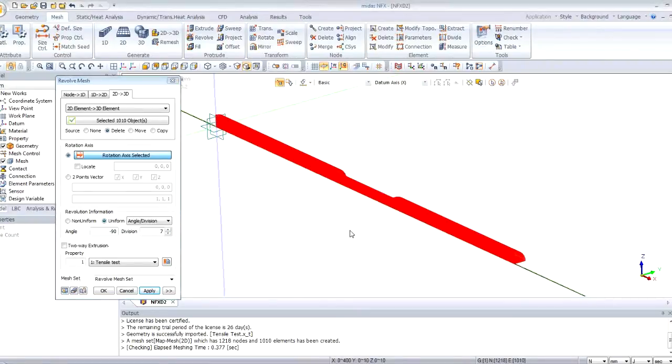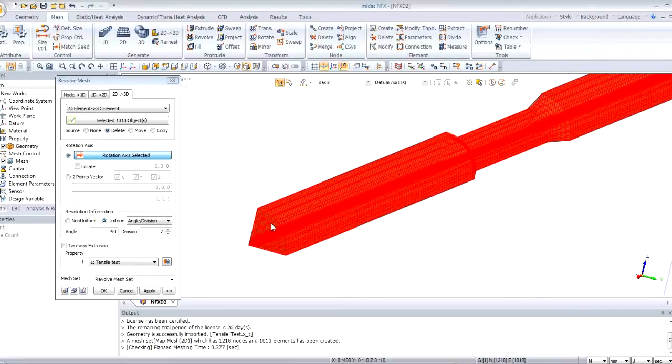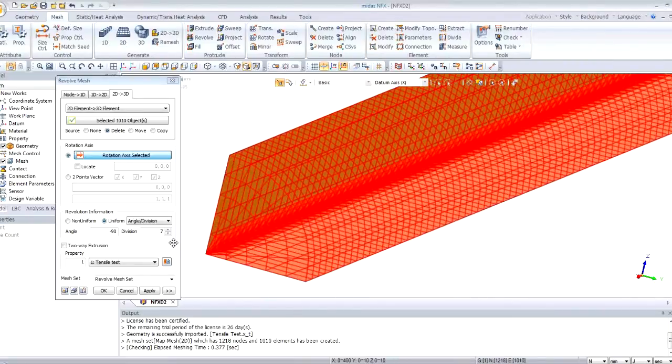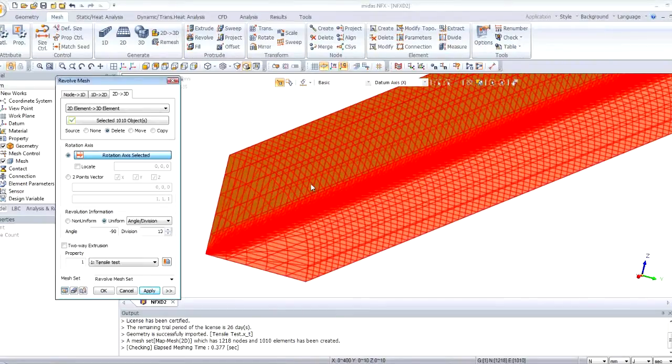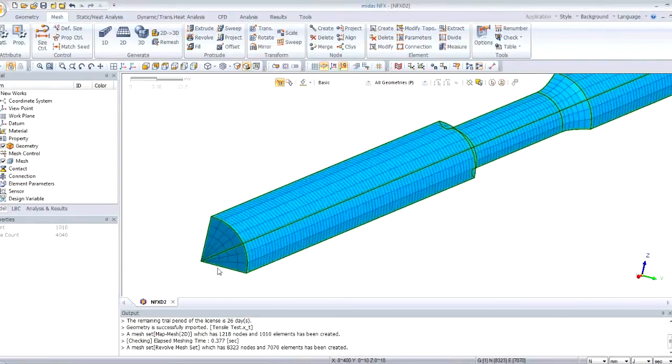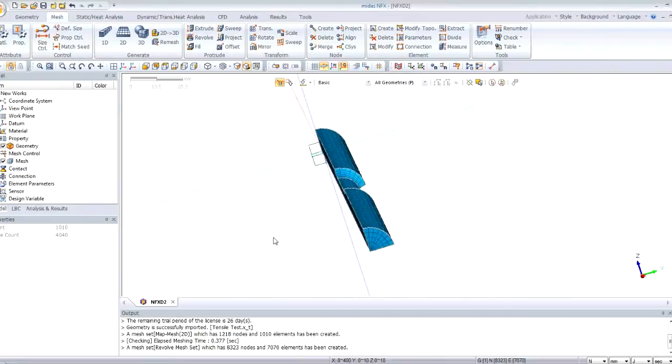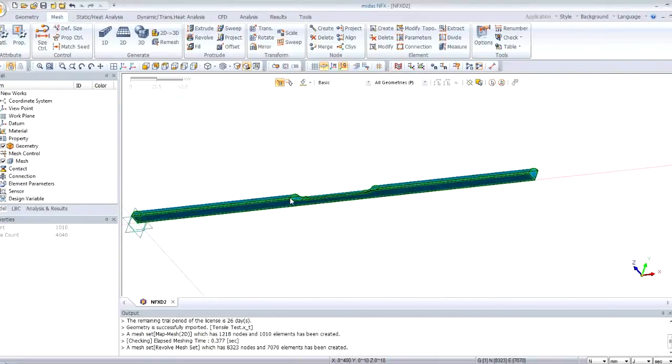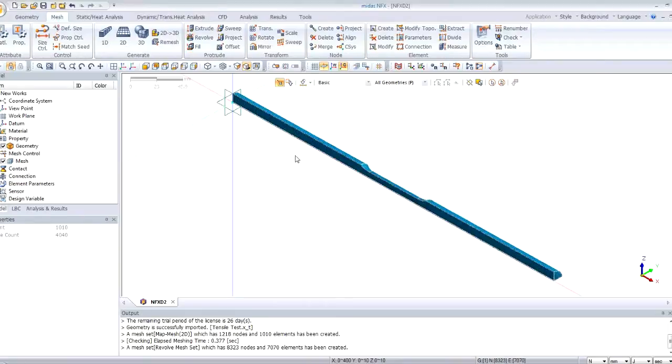Let's look at the preview. Let's zoom a bit to view. Looks good. So if I increase the number of divisions, let's say if I choose 10, it will look like that with smaller mesh, but actually it's a bit too small, so I just choose 7 and click on OK. Okay, now I got my mesh, so I can begin to assign the boundary condition to all that.